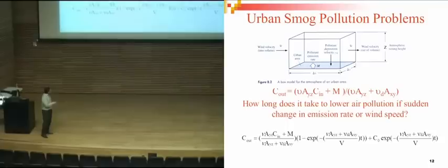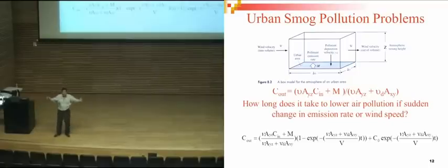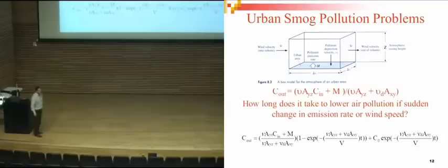So we have to go into our, again, you'd be given this solved solution for the differential equation. But the first thing when you hit these problems, you have to ask yourself, is it steady state or not? We're looking at a change in concentration over time, so it's going to be non-steady state. Conservative or non-conservative pollutant? Conservative? I know it's the end of the day on Thursday, but this will wake you up. Conservative. Yes, it is a conservative pollutant. We haven't changed anything with respect to lead, no reactions. Those conditions are the same.